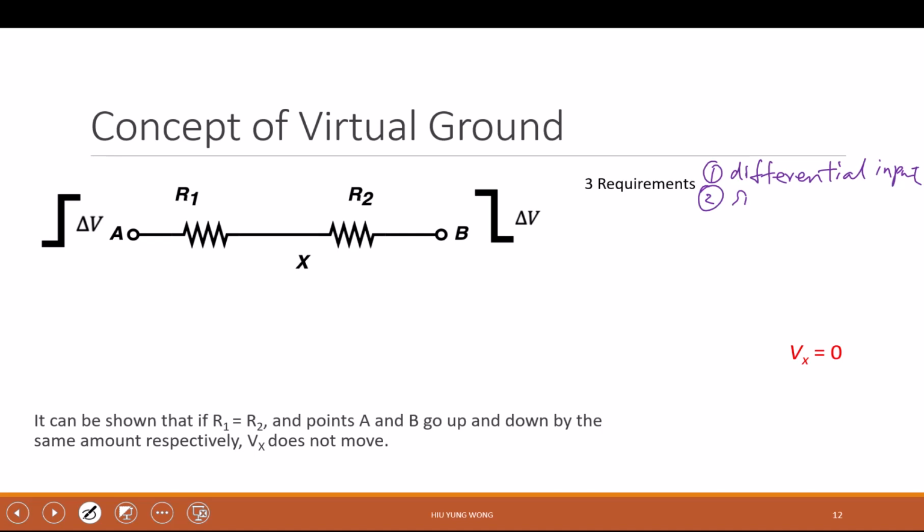Second, you need to be a small signal. The reason that you have small signal is because we linearize the circuit. Right? Like what you just asked me, the best is the smallest the signal is, almost 0. Okay? And third, you need to have an absolutely symmetric circuit. I will keep emphasizing this one.